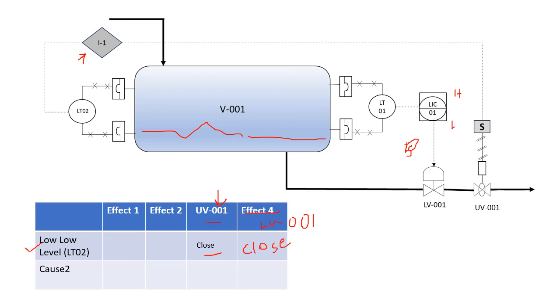But again, you can obviously cross check between the P&ID and cause and effect, and there will be situations where you will find that there is a mismatch between the tag numbers or some other things between the P&ID and the cause and effect diagram, and that is when you should point it out, and there is a major concern.